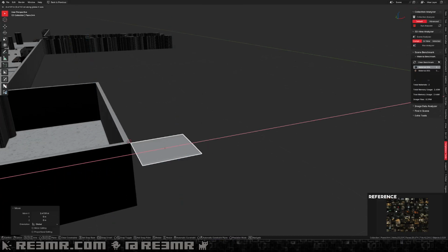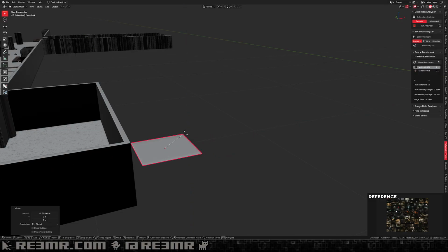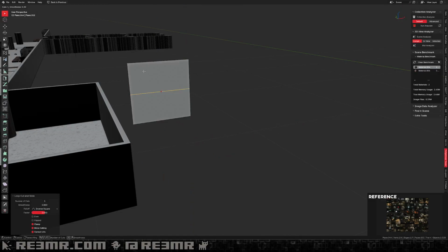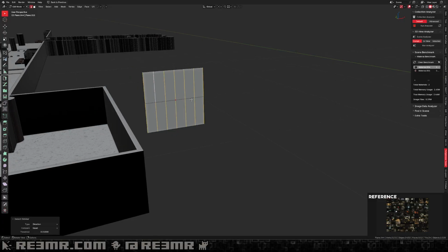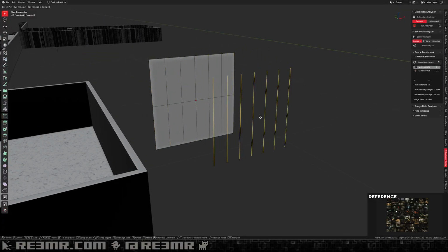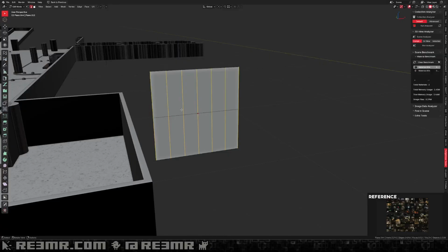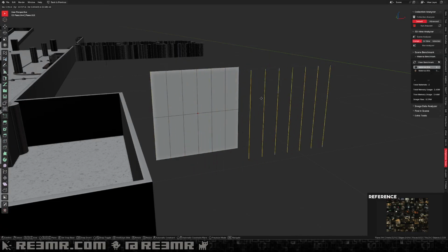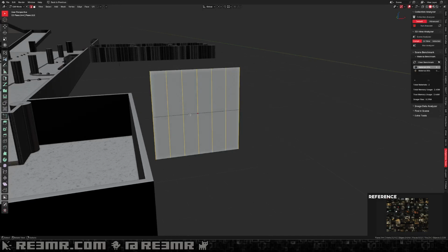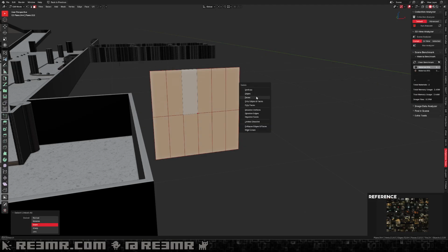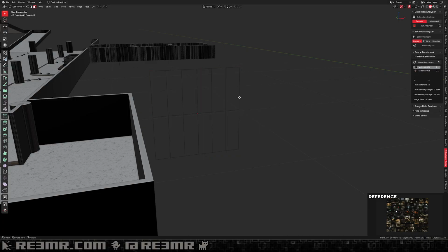And that is just to not dissolve the faces at all. Just to keep it like this, right? This would be the railing. And then do something like this, select by direction, and then just do the split like normal, which means now it's like a duplicate, like it's still on the plane there, but it's also here, if that makes sense. Select this by direction, press Y to split. And now when that's done, I can select one face and select linked, and delete. We can delete the vertices here, which leaves us with only what should become the